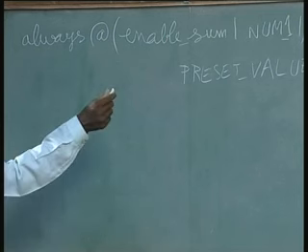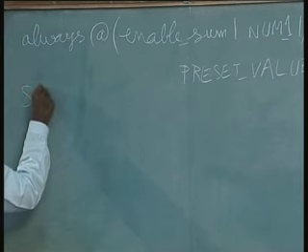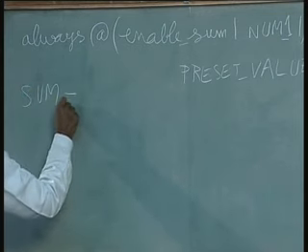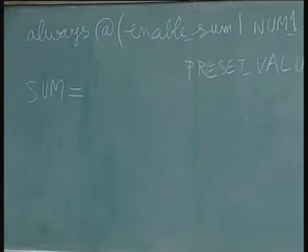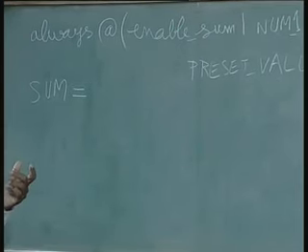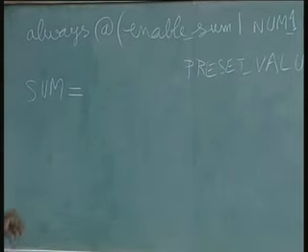For example, you want to have a sum output. So, all we have to do is just write sum, then equal to, now what we have also learnt earlier is how to model a mux as such. We will combine that mux in this always loop. Normally you should not use an assign for a mux inside the always block. So, that is the difference here.